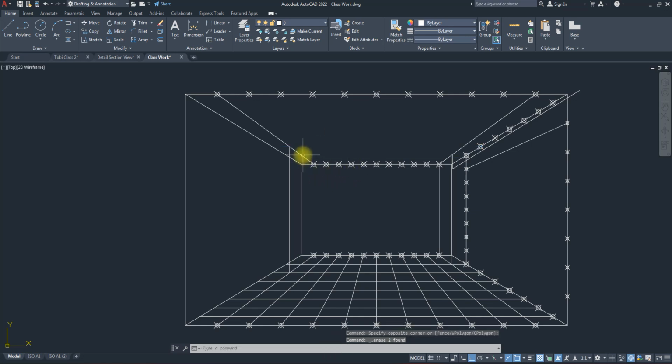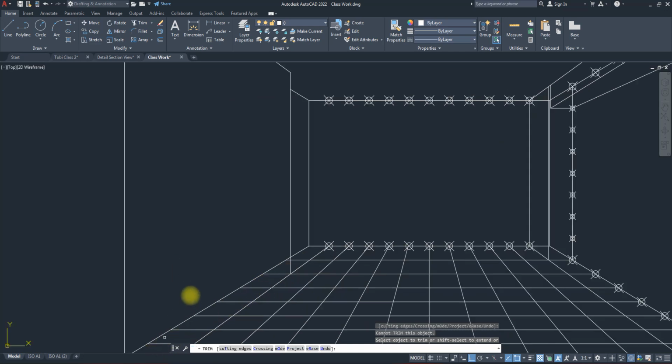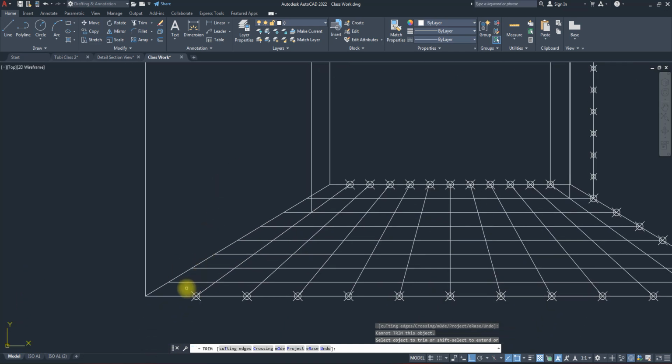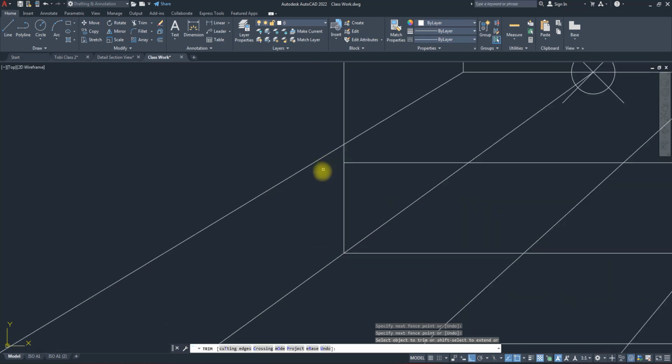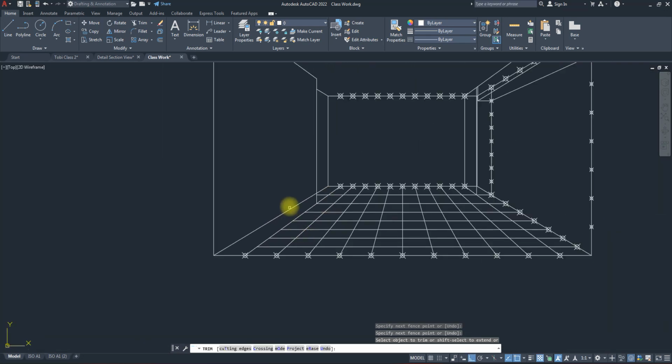And this one, I'm going to trim this guy out. So I'll just use my trim command to trim this. Are you seeing that this is beginning to come out? So this place also, I'm going to trim this. We now have this. Do you get that now? The top part. So we're coming down. We know that we're going to trim this guy all the way to this place. Okay? We are going to trim this because we are not going to see this, because this line, this part of the wall, would have covered this place.